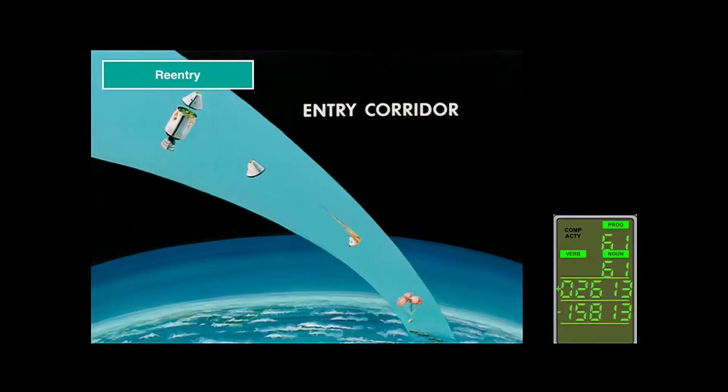Once in orbit around Earth, re-entry parameters are calculated on the ground and transferred to the Apollo guidance computer via S-band uplink. The first entry program, P61, entry preparation, starts at entry minus 25 minutes. Various landing parameters are requested, like latitude and longitude of the splash zone, as well as the velocity and angles to enter the atmosphere.